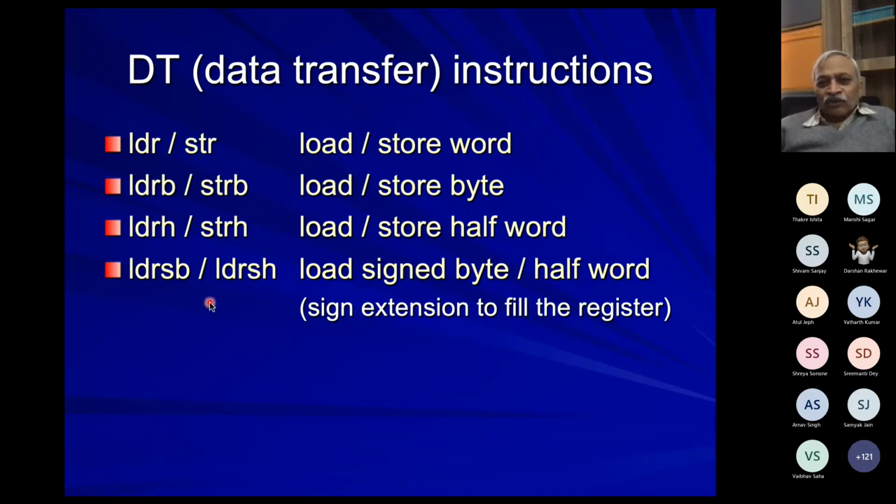So if you have loaded 8 bits, which is a negative number in 2's complement form, the leftmost bit will be 1, and then the bytes which are not being loaded now will be filled with that sign bit. This is called sign extension.